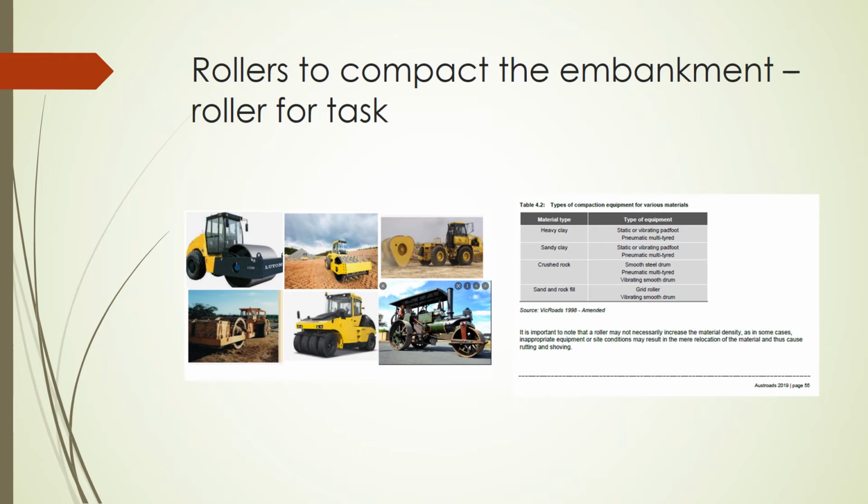If you're using rock fill, however, you want to use the grid roller and the impact rollers, which are the bottom left and the upper right pictures. Very effective at dealing with those larger block sizes and breaking those and compacting those larger rocks into a more stable base.